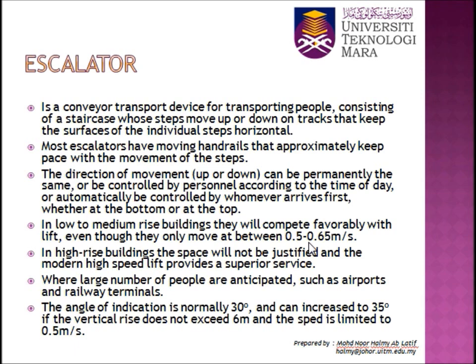In low to medium rise buildings, they will compete favorably with lift, even though they only move at between 0.5 to 0.65 meter per second. In high-rise building, the space will not be justified, and the modern high-speed lift provide a superior service.